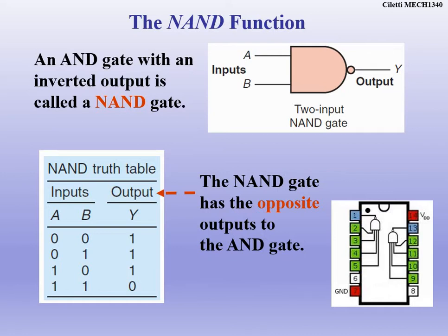Okay, and I talked about this one before. This is a NAND gate. All right, it means not AND. So when you do this, it's the exact opposite of an AND gate. Remember, the output truth table for an AND gate was 0, 0, 0, 1. The output for a NAND gate is 1, 1, 1, 0. It's the exact opposite. Why? Because we're inverting the signal after we AND it. So here's how it kind of looks, all right? The NAND gate looks just like an AND gate. We got that bubble on it, though, so we're inverting it. So it's pronounced a NAND gate.